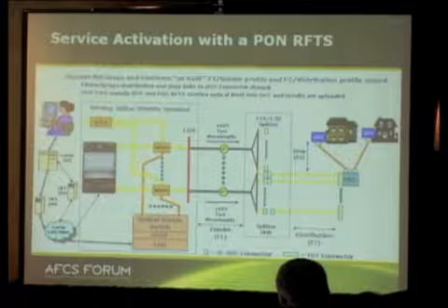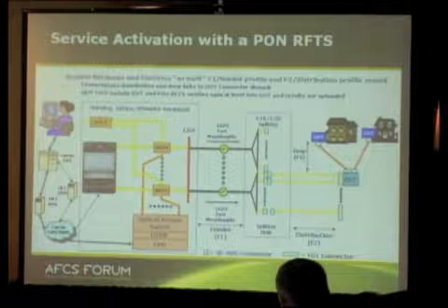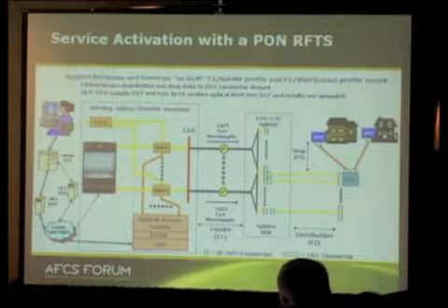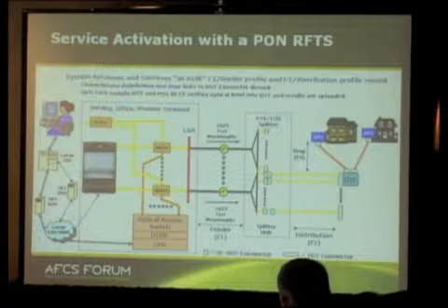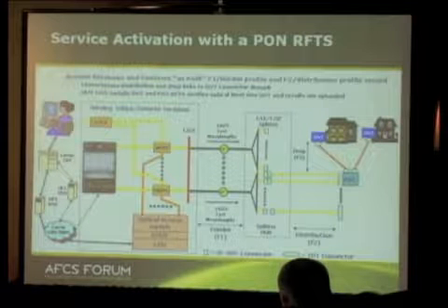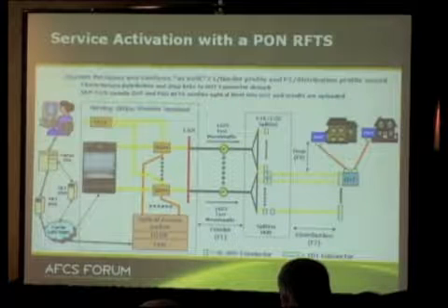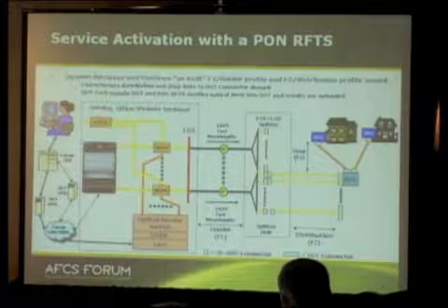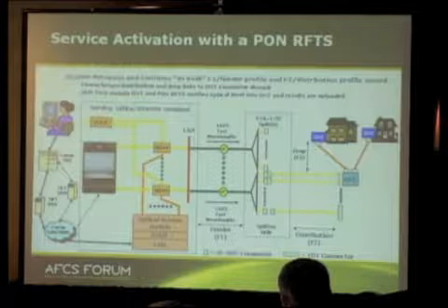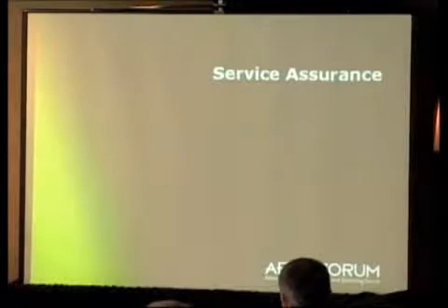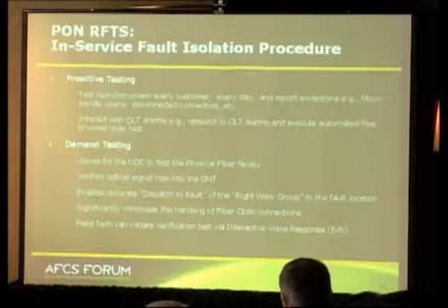Initially people were splicing their splitters in the cabinet, and now pretty well everybody's doing connectorization. So if a new splitter had to come in, the whole process begins. It says that particular cabinet with those splitters is full. I put in my next splitter. He would go ahead and verify that the F1 is good and go through the whole process of building the onion, as I call it. So that's on the installation side.